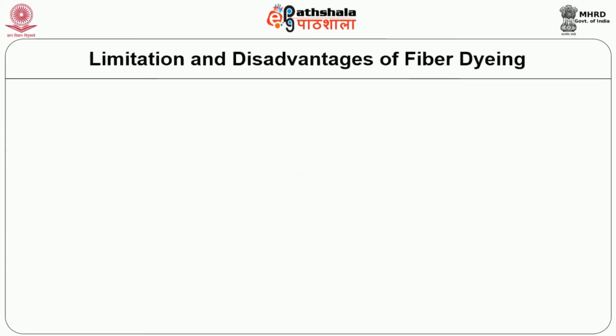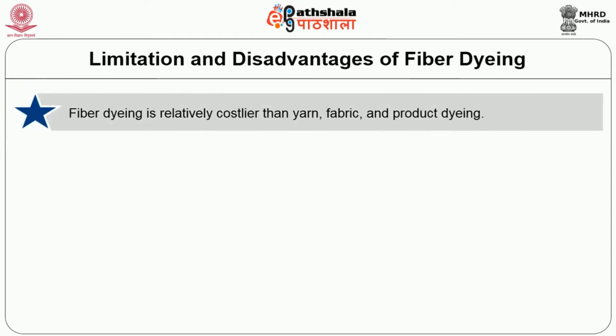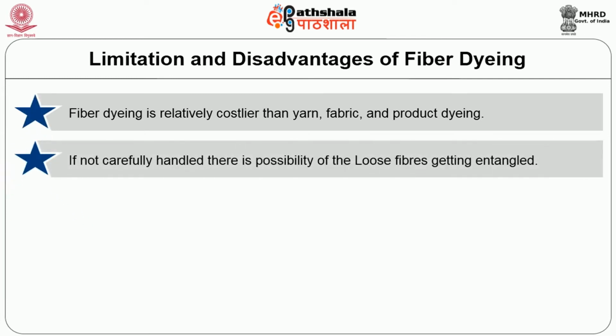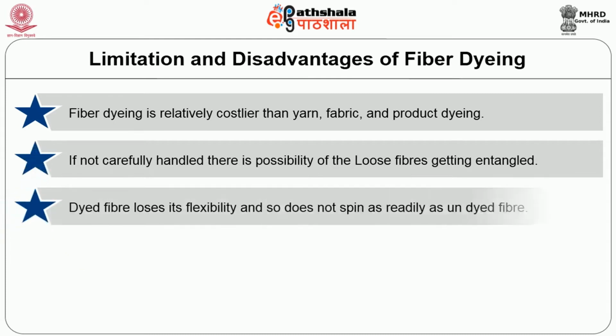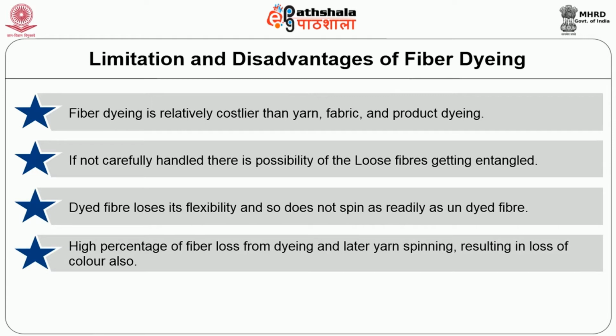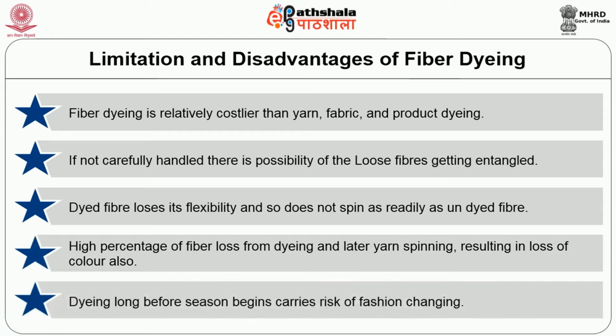The disadvantages are: fiber dyeing is relatively costlier than yarn, fabric and product dyeing. If not carefully handled, there is possibility of the loose fibers getting entangled. Dyed fibers lose their flexibility and so do not spin as readily as undyed fibers. There is a high percentage of fiber loss from dyeing and later yarn spinning, resulting in loss of color also. Dyeing long before season begins carries risk of fashion changing.